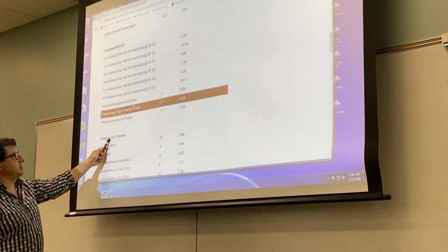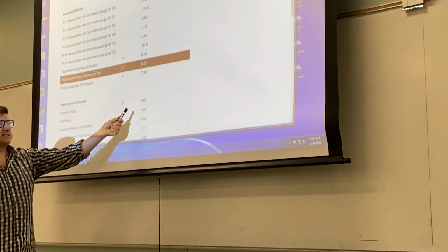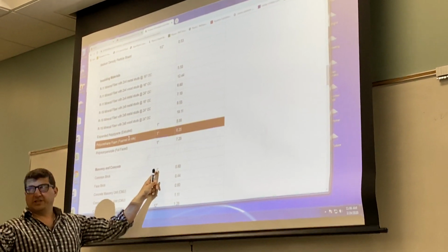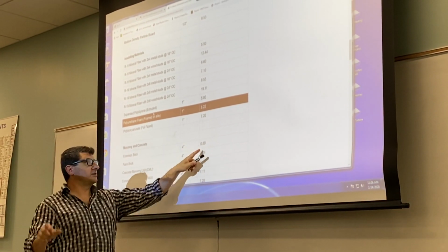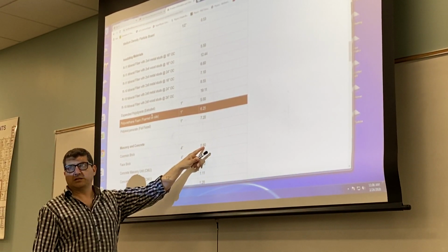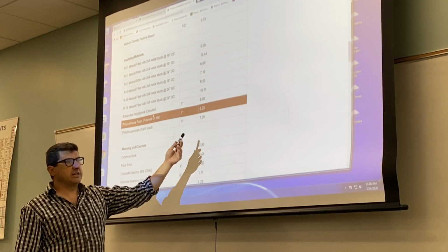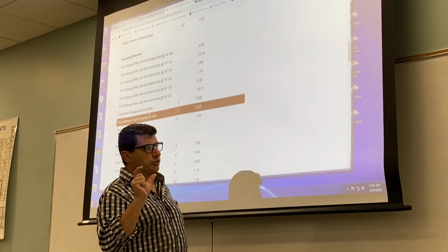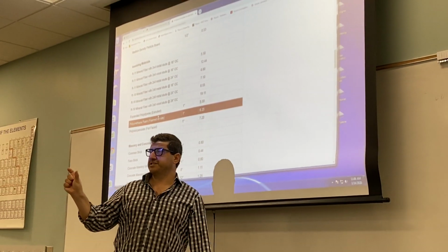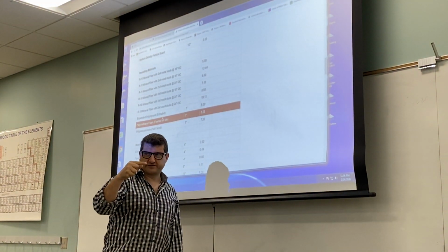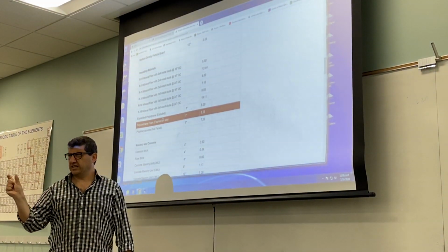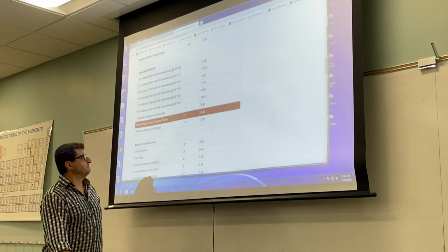Then you got masonry on concrete. So those are not very good insulators. A 4-inch brick, it's very, very thick, it's only 0.8, you see. And 0.8 literally means it takes 0.8 Fahrenheit difference to cause 1 BTU to transfer. You see, 0.8 is not that much, you see.